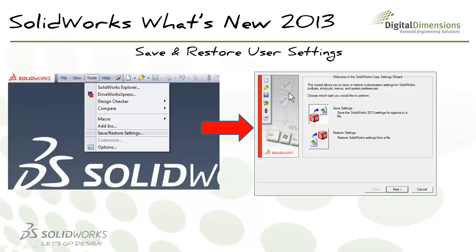The one detail I want to point out is you do have to close all current open models in the SOLIDWORKS session to use this particular ability. But the trade-off is that you don't have to go through that convoluted menu structure of Start Menu, All Programs, SOLIDWORKS, SOLIDWORKS Tools, Copy Settings Wizard. It's all embedded within SOLIDWORKS.